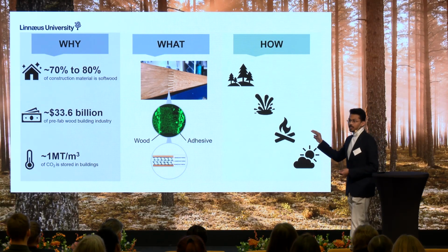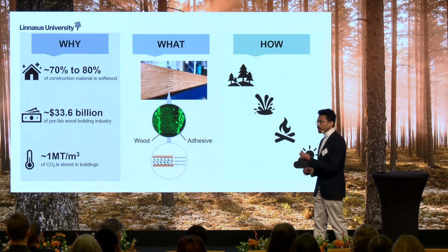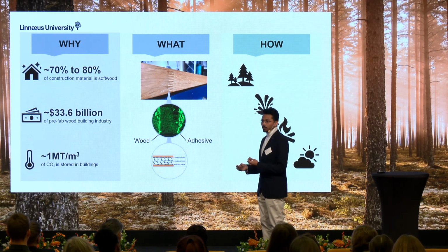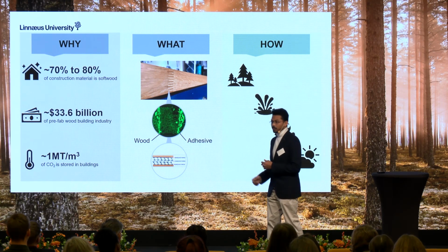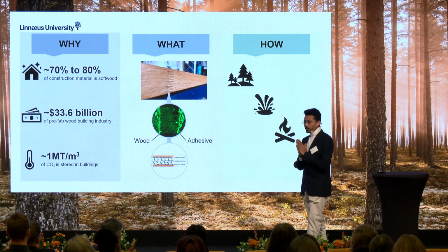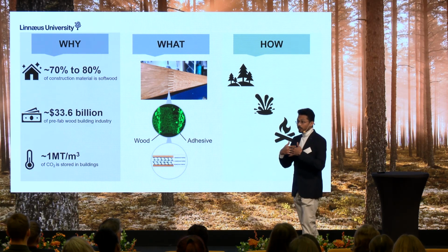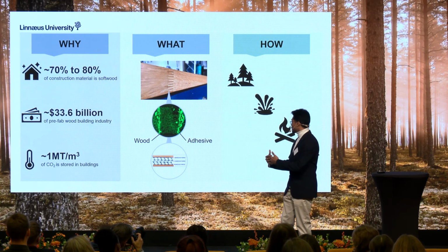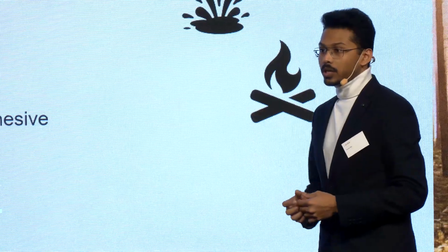Firstly, I'm changing the raw materials. I'm looking into the glue. If we are changing the glue, the rheological properties affect its adhesive penetration. And when we are gluing edge-wise or end-grain-wise, we can see the difference. Next, we are looking into the moisture movement in the wood.